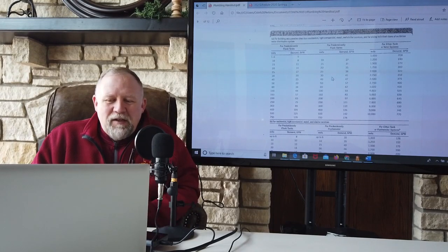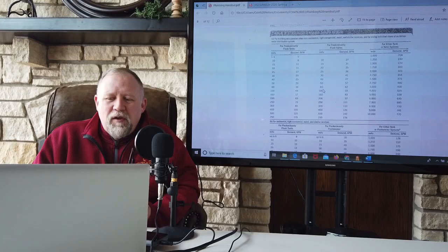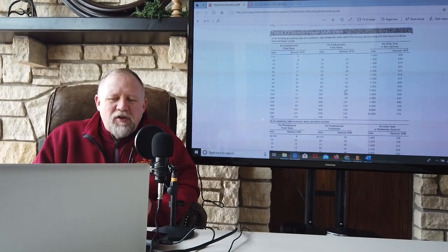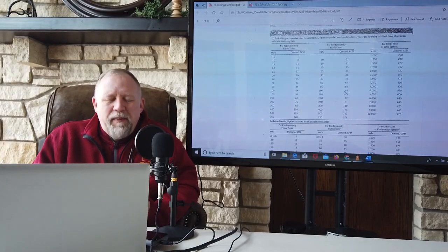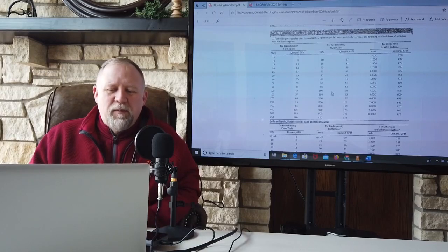Now, what you can do, though, is let's say on your final project or something along those lines, maybe you do fall between like 80 and 100 water supply fixture units. What would you do there? Well, you can interpolate between two values. Okay, that's fine. That's not a large interpolation, and so it'd probably be valid. But just do that. Interpolate between water supply fixture unit values to get you your gallons per minute.